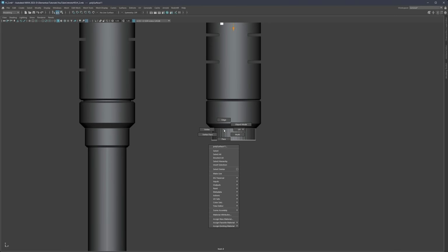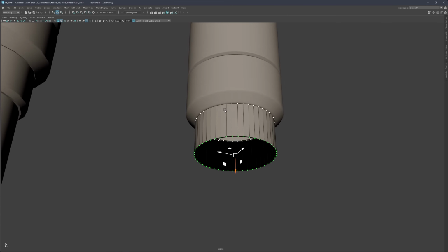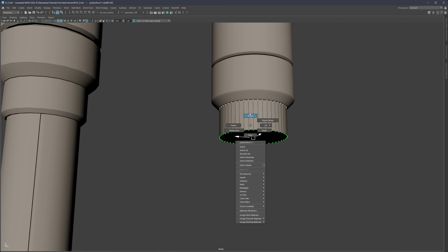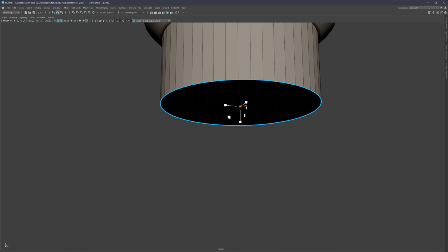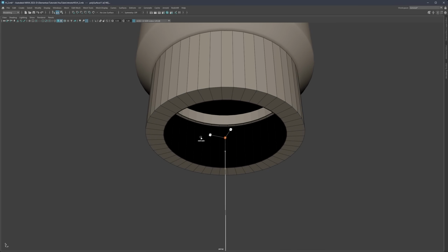So let's go ahead and align these vertices, making sure camera based selection is on, and by holding V I just want to make sure that I match to this point, like so. And let's go again to edge mode, double click the edge, and in scale mode I want to hold Shift and simply extrude this on the inside till somewhere like here.